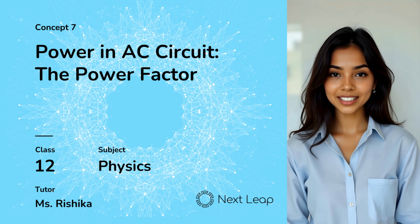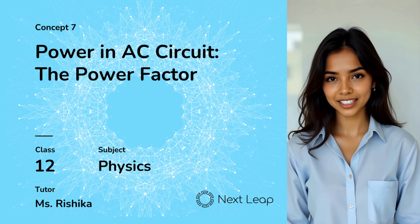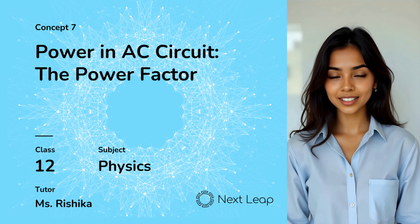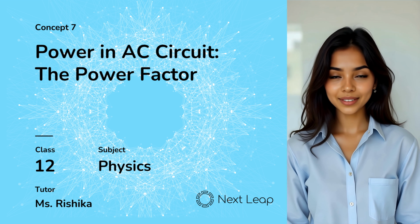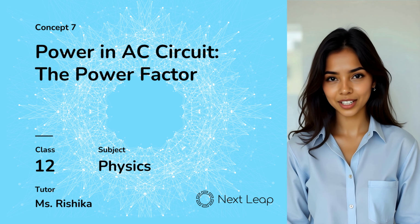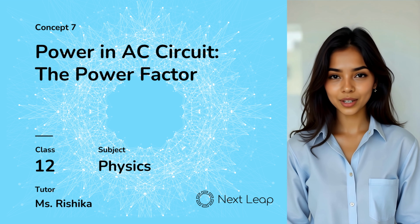The voltage across an AC source is V of t equals Vm sine omega t, while the current is I of t equals Im sine of omega t minus phi. Multiplying them, we get instantaneous power P of t equals Vm Im sine omega t times sine of omega t minus phi. After simplification, it splits into two parts, one steady term proportional to cosine phi and another rapidly oscillating term with double frequency. The oscillating part averages out to zero, leaving only the steady contribution to average power.